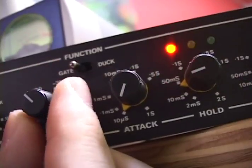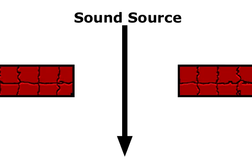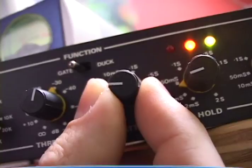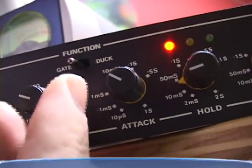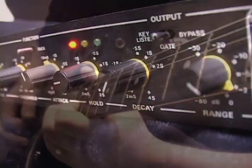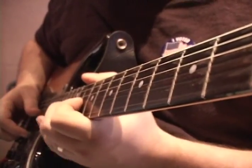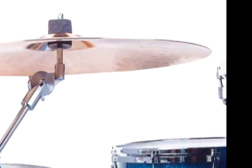When the singer starts up again, the threshold will be exceeded and the gate will open back up and let the sound pass. Again, similar to a limiter, you'll generally find control over attack and release, so that the effect can appear to happen naturally. In particular, if the release is too short, then a nice slow fading sustain on a guitar or a trail of a cymbal hit could get cut off abruptly.